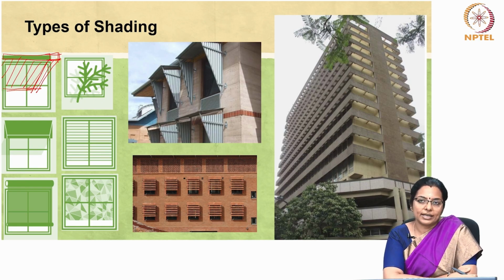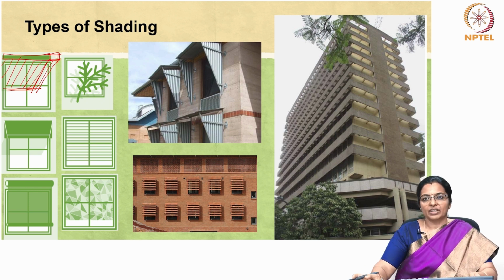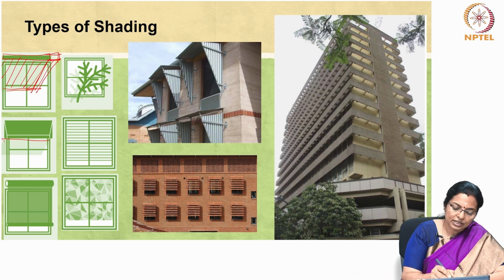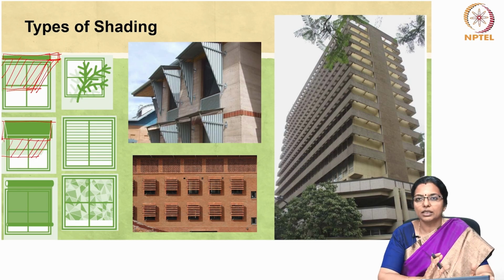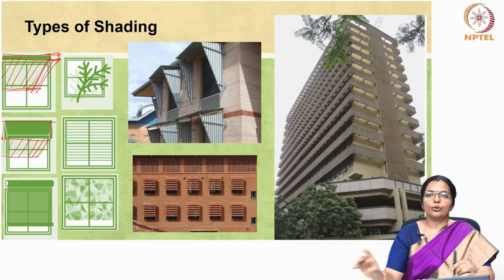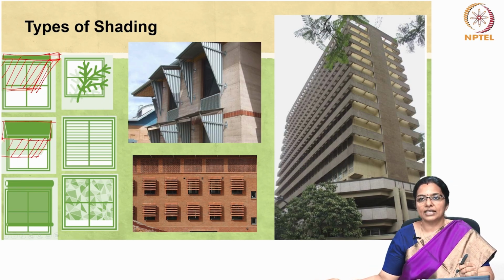Then second is awnings. Awnings, like overhangs, block sun effectively. Awnings often extend further than overhangs, and normally they are considered to be best on east and west facing walls. So, these are awnings. However, on all the walls, what works best, at least in the tropical country, is overhangs at least. Then you can have exterior roller screens or shades and shutters.